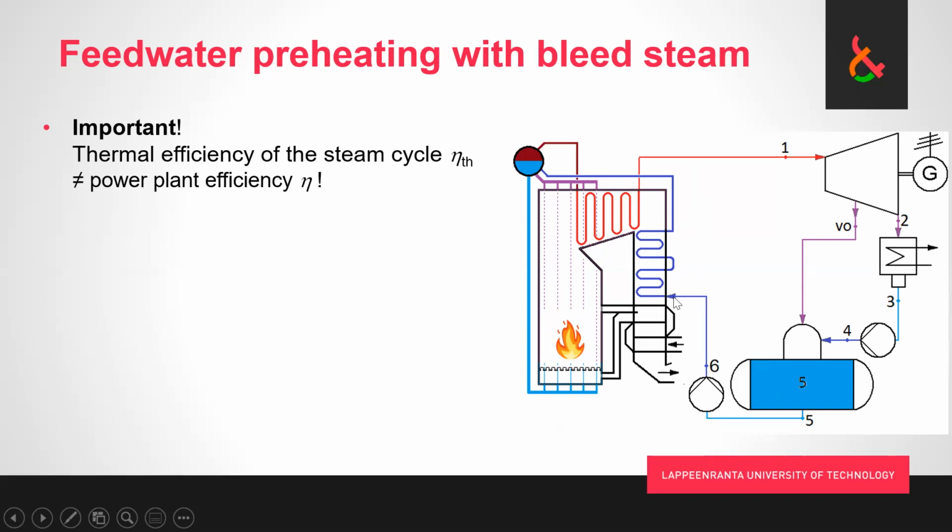But that's going to come at a cost of putting hotter and hotter flue gases into the air, and boiler efficiency is going to go down, and that's not going to be helpful for the whole power plant efficiency. So that is something to keep in mind, that the ultimate final goal that we're looking at is improving the power plant efficiency.